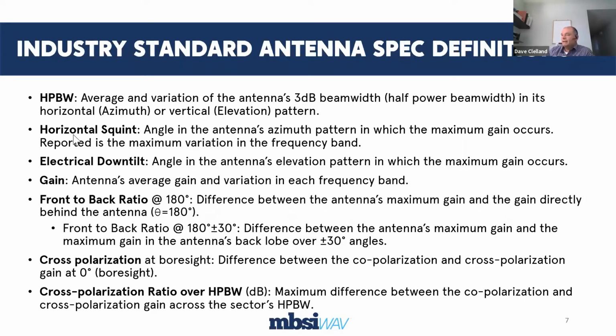Squint, I mentioned the horizontal squint here. When we have a case of an antenna like the one that I showed in the example here a few slides back, the elements affect each other. And so the fact that all of these radiating elements are within very close proximity to each other tends to flatten out this attenuation value wider than what the half power beam width is.